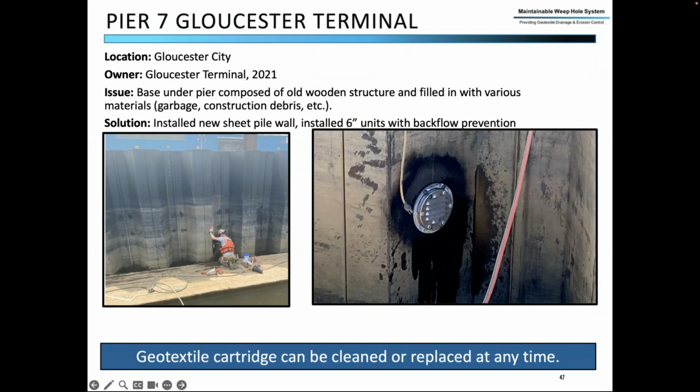First, I want to bring up that we do a lot with seawalls, and I don't know if any of you are doing seawalls. I bring this up not because it's a seawall, but because this is an example of new construction where the weep hole filters had been specified based on a certain type of backfill that the engineer had put into the design.